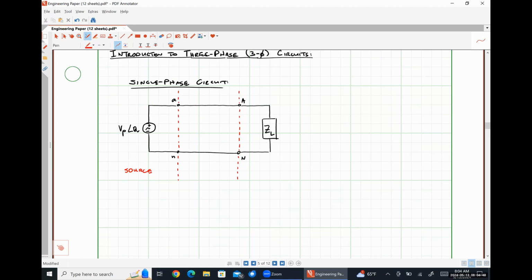Realistically, that's not technically true because in our home, well, I mean, it could be this. So in our homes, typically speaking, even though we get 120 volts RMS out of our outlets, our homes are supplied with 240 volts RMS in a split phase system. So we have a single phase, but that 240 volts is split into positive 120 and negative 120. And so we can power low current draw loads with just 120, and then higher current draw, higher power loads like our ovens, dryers, and all of that kind of stuff with 240. But anyway, that's another bag of cats.